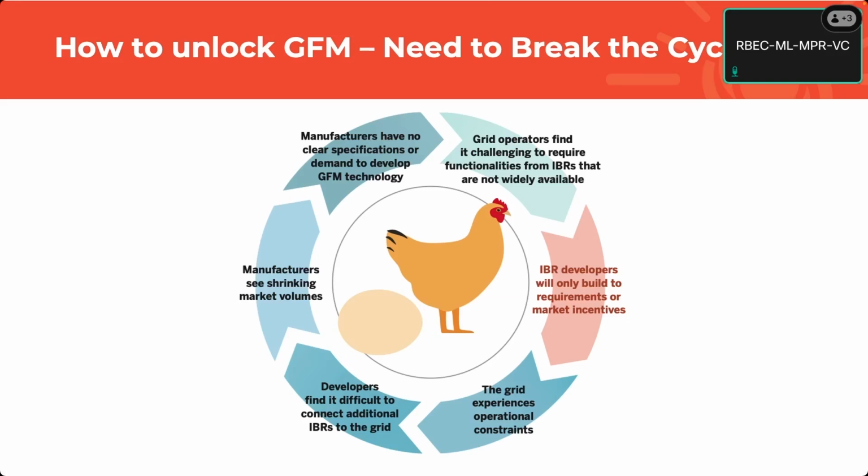So we go back and go through 2 weeks of detailed control tuning, the old fashioned stuff, trying to get extra stability margin out of these controls the hard way, adding extra functionality to tune this out. And now it's barely stable, still in grid following mode. But there are more inverters coming in next year, so we're for sure going to see another event. But the utility refuses to turn on grid forming because it's too scary. That's frustrating for me because we can see it in the models. It's definitely going to work.